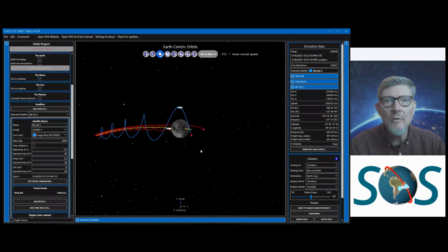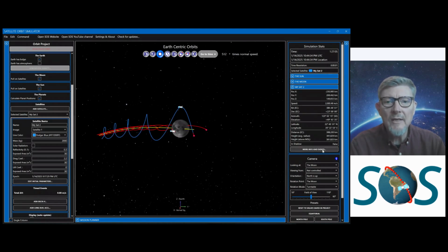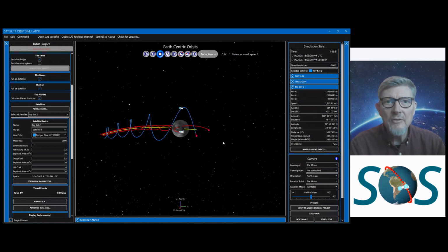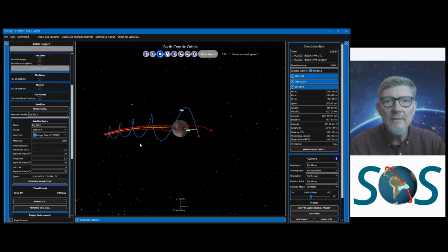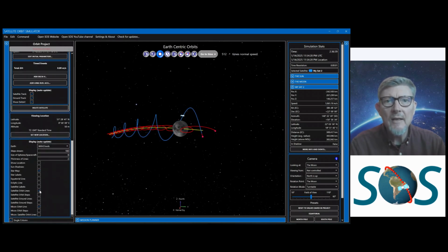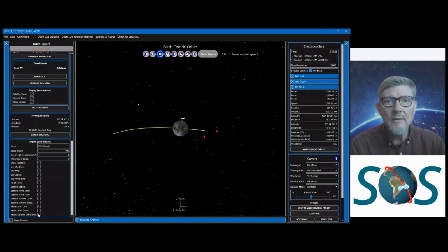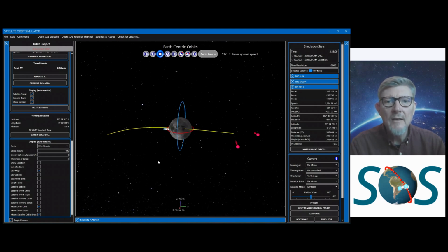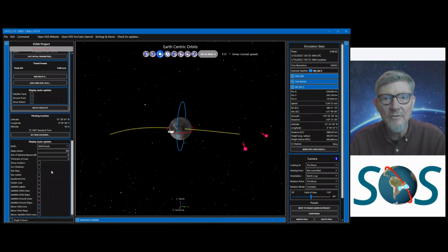If we could see the orbits relative to the MCI coordinate system, you might better understand the lunar orbits. Let's do that now. Uncheck the Satellite Orbit Lines checkbox, check the Moon Satellite Orbit Lines checkbox, and run the simulation again. Now, the satellite orbit lines are shown relative to the Moon.